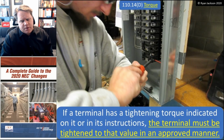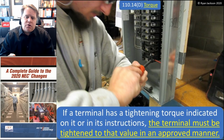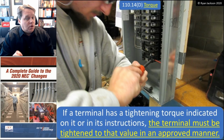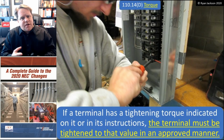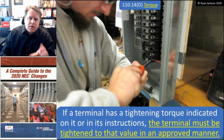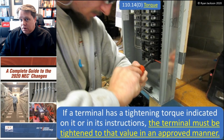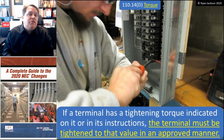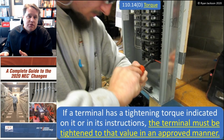Now, the other thing that happened is in 110.14(D), and that's having to do with torquing our terminations, a very important concept. If a terminal has a tightening torque indicated on it or in its instructions, then the terminal must be tightened to that value in an approved manner. All right, so the concept of torquing our terminations is certainly not new. For decades, we had an informational note here that just told us, listen, some equipment has a tightening torque and you need to follow instructions. And that was the end of it. It wasn't necessarily a requirement, just a reminder that some equipment does have a tightening torque.